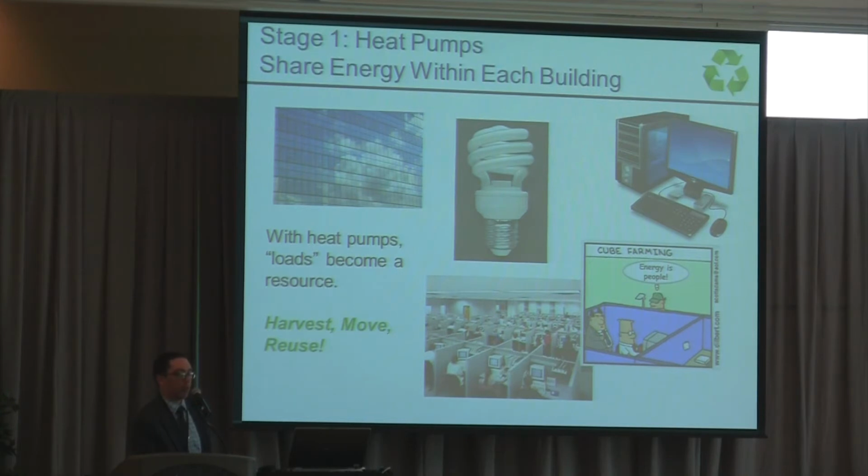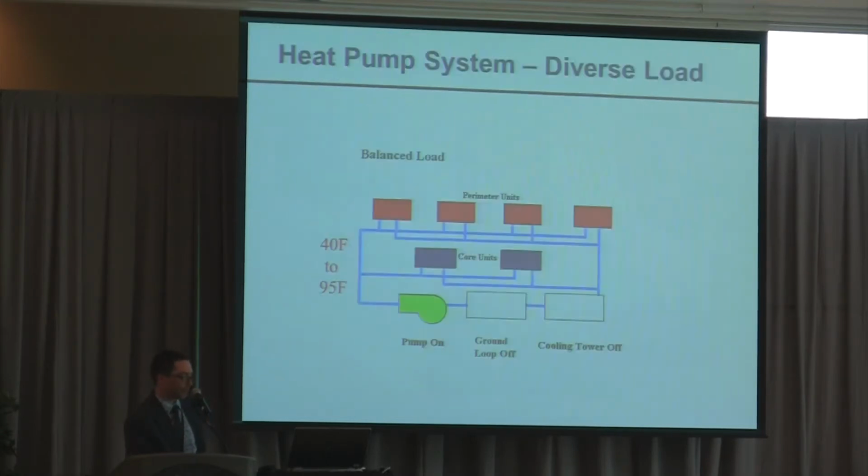That ability to recover and move heat presents a lot of opportunities. All of a sudden, all of these things that engineers typically consider to be loads, that we have to deal with in some way, can actually become an energy resource. Whether that's computers, equipment, lighting, people, human bodies, 250, 300 BTUs an hour. All of these things, solar gains, all of these loads that typically just become a liability that we have to get rid of, become a resource. And the question is, okay, how do we capture that using the heat pumps? And then where can we reuse it?